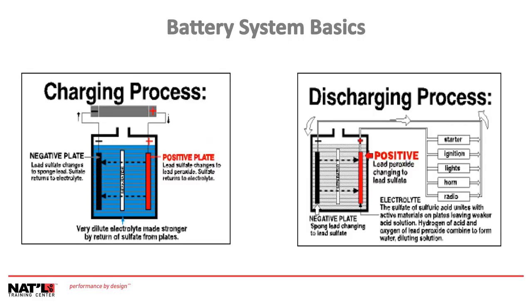A battery, which is an electric cell, is a device that produces electricity from a chemical reaction. Strictly speaking, a battery consists of two or more cells connected in series or parallel, but the term is generally used for a single cell. A cell consists of a negative electrode, an electrolyte, which conducts ions, a separator, also an ion conductor, and a positive electrode. The electrolyte may be aqueous, in other words, composed of water, or non-aqueous, which means not composed of water, in liquid, paste, or solid form.